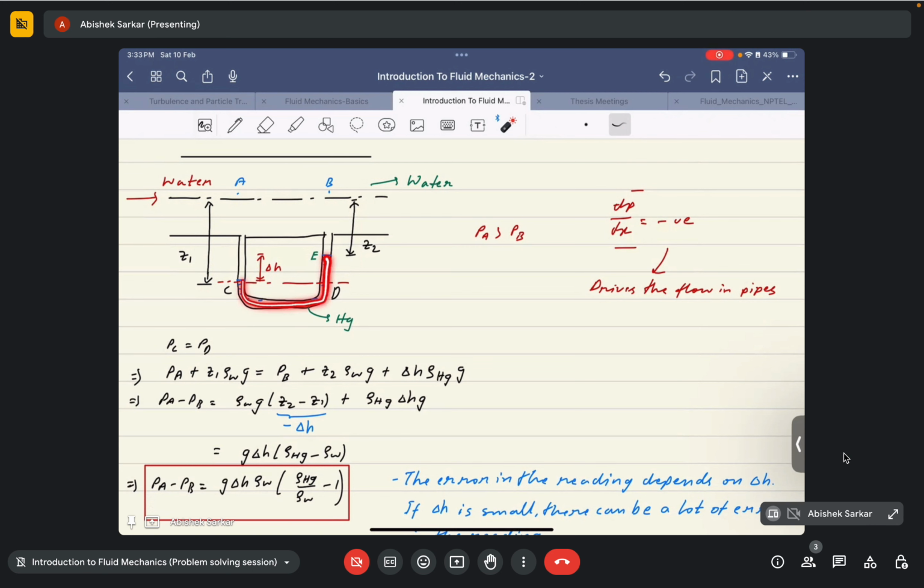Now what we'll do is compare the two heights of mercury in the U-tube shaped manometer, and choose the lower level as our datum. Datum means the point of reference from which we will measure our pressures. So we consider point C, since it is at the lower level, to be our datum.